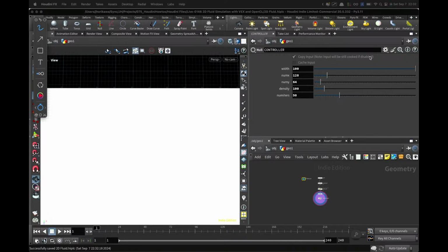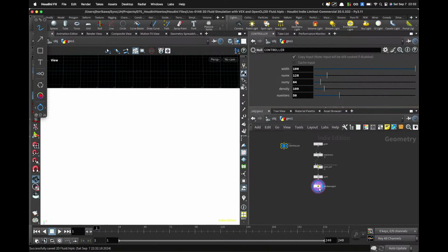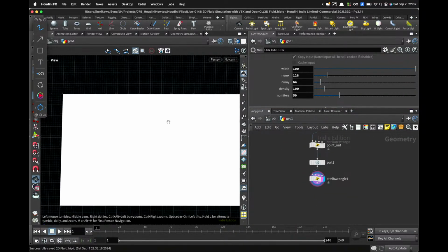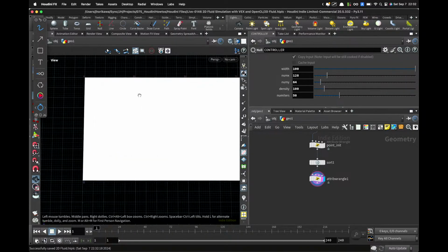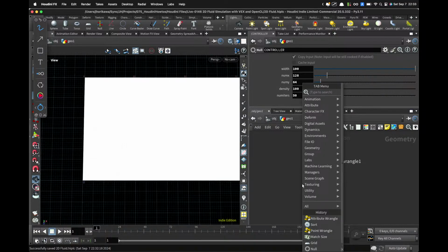Okay, so you have 3 pieces of information to add to this. So for the initial u value, in the example that I showed you previously, I have just set the u value for the left hand side points to be equal to somewhere around 1 or 2, so that it goes to the right hand directions. So let's create that value first.